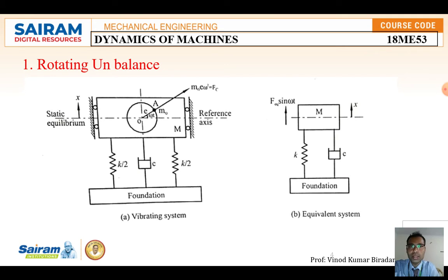One of the most important applications of forced vibration is vibration due to rotating unbalance. This is one of the most important factors. The unbalance occurs because all manufactured rotors have some eccentricity, that is, some displacement takes place. As of now there is no rotor which has zero eccentricity. This may be due to the presence of small defects, such as casting defects and non-uniformity in manufacturing.